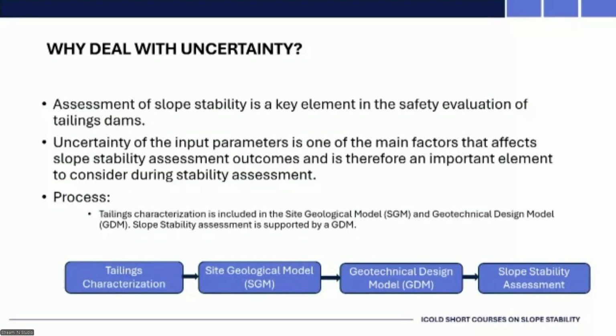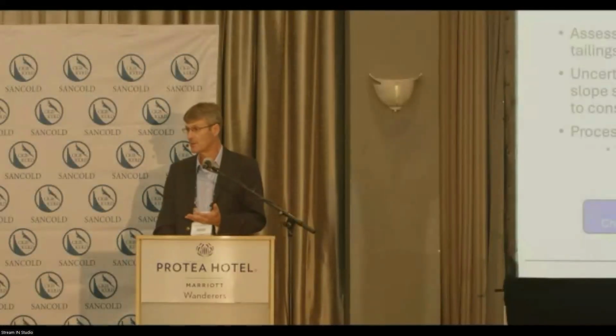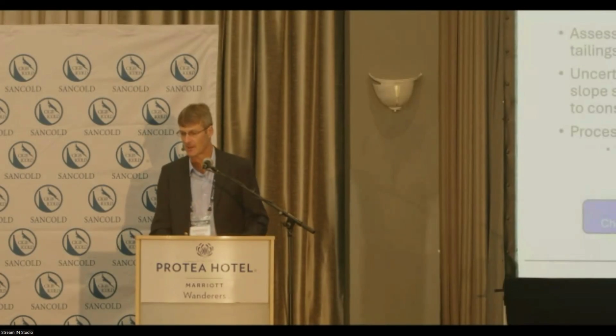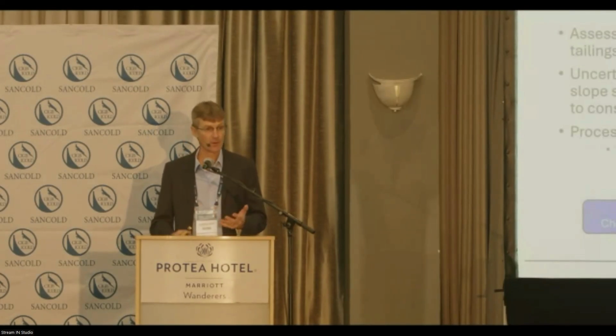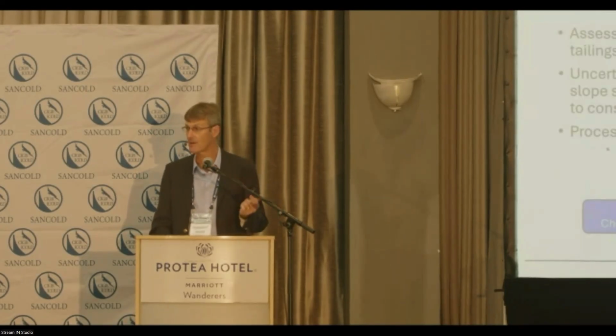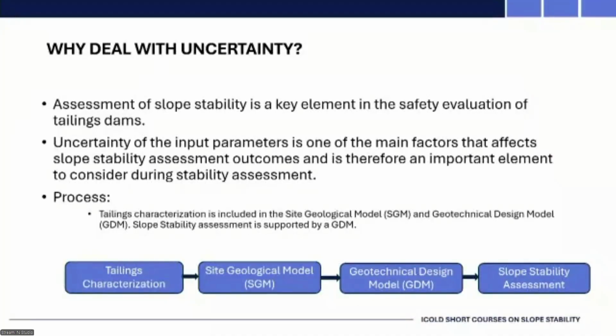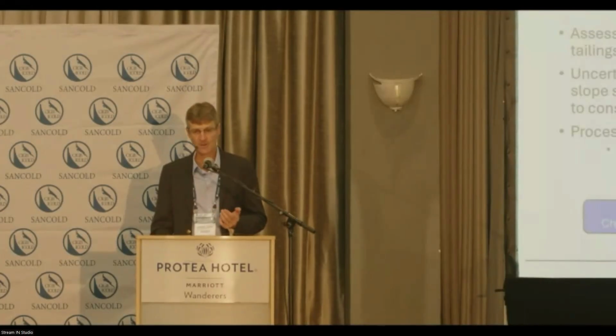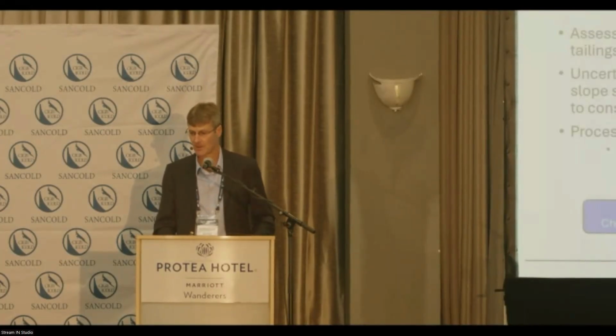So we have to go out and we have to model the site. We have to do all our foundation investigations. And generally with a new tailings dam, you've got the opportunity of doing that up front. And there's no excuse for not getting good geotechnical data at the beginning of your project. If you have to come back later, it's a lot harder and a lot more expensive. And then you put together the geotechnical design model, which then incorporates the foundations plus the structure on top of it. And that then feeds into your stability analysis. So that's the model that's been put together in terms of the ICOLD Bulletin 194. It suggests that you follow this process.